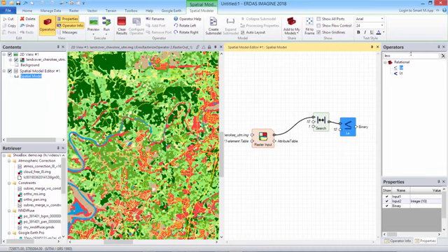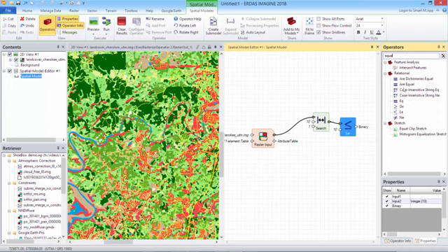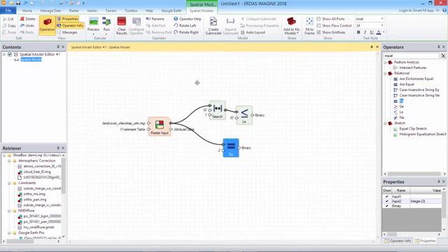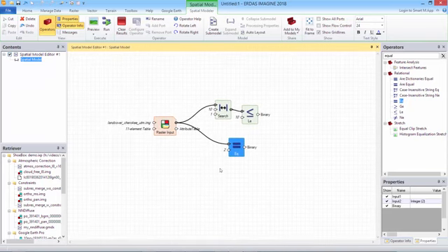We also want to find the class locations of forest. So we want an equals in that instance, and we basically want to bring in our raster input and say, okay, if the original raster input class is the recode value of 2, i.e. forest, those are the other locations that we are interested in. Let's give ourselves a little bit more room to work with here. We could zoom in or zoom out, but for the training I'm going to just get rid of the 2D view.